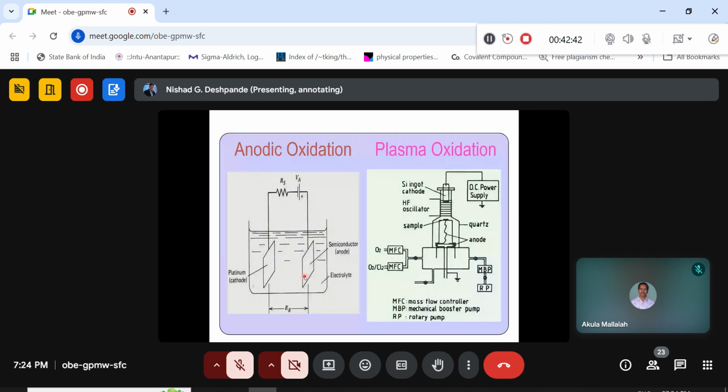Okay. So in that case, if you cannot control the voltage properly, then naturally the whole of the OH minus will suddenly come and gradually they will form Helmholtz layers here, and slowly you will have a hydroxide or an oxide layer which is uncontrolled. Okay, so that's why this anodic oxidation process is not very well utilized in the fab processes.